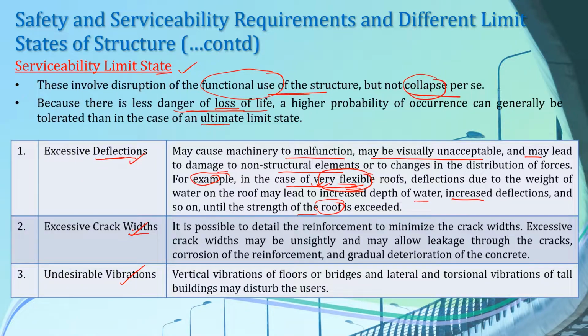So another serviceability limit state can be excessive crack width. It is possible to detail the reinforcement to minimize the crack width. Crack widths are not bad per se, because the reinforced concrete elements should crack in order to perform their function.